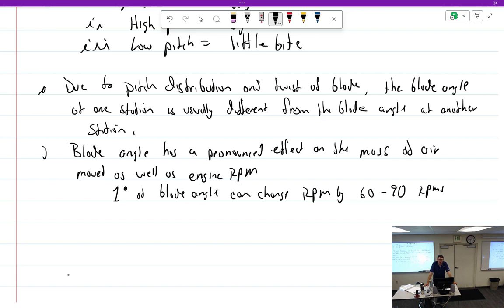When you are working on an aircraft with a fixed pitch propeller, one of the things you have to do on an annual inspection or 100-hour inspection is to determine the, do you guys know this one? Static RPM. So static RPM is what RPM the engine will achieve with the aircraft not moving forward.